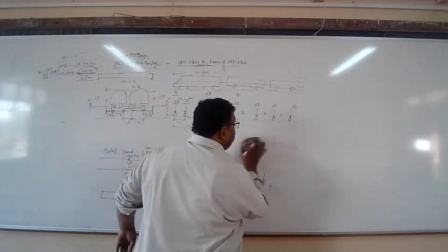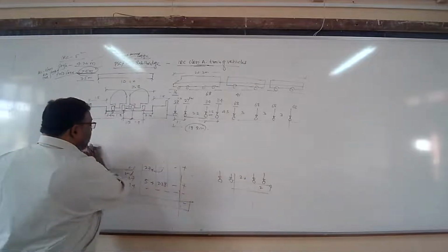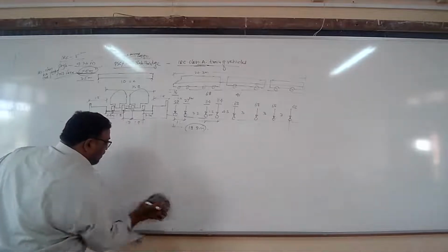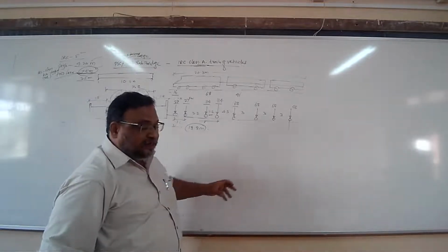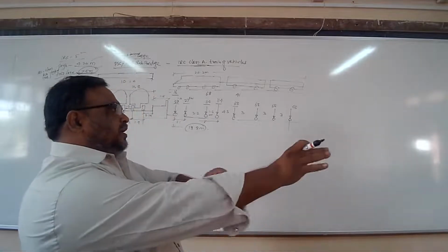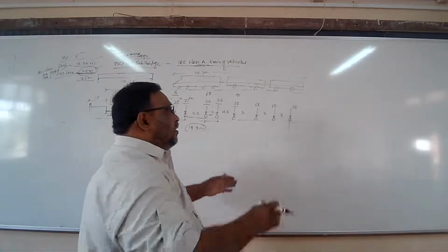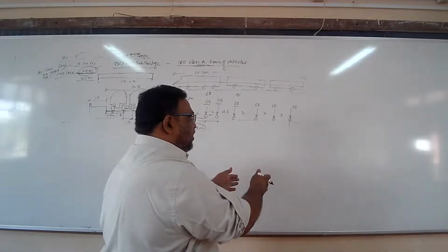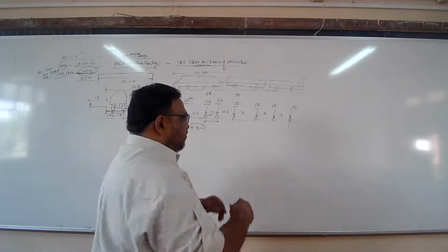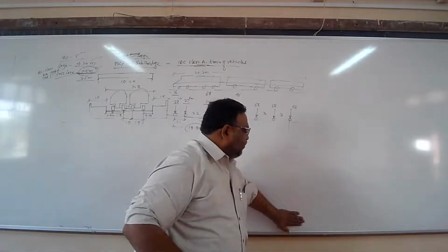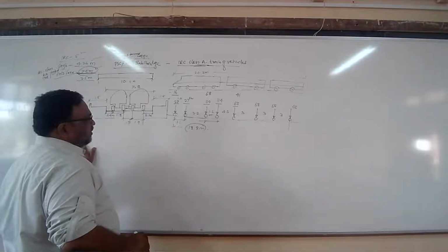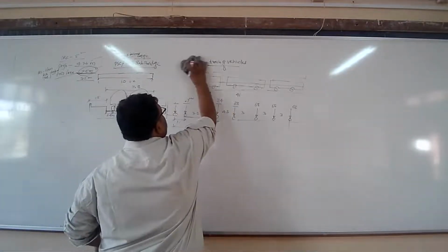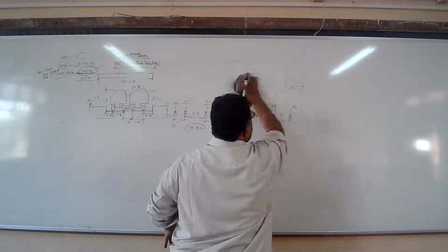After that, what did we do? How did we identify the position of the vehicle? When we identified which of the loads is crossing, that load which was crossing from the center line and the resultant of all the loads which were acting on the bridge, those two we had placed symmetrically with reference to the center line of the bridge, equidistant from the center line of the bridge. And the exact position of the vehicle was identified. So what was that exact position of the vehicle? Because that is very much required here for the load calculation.